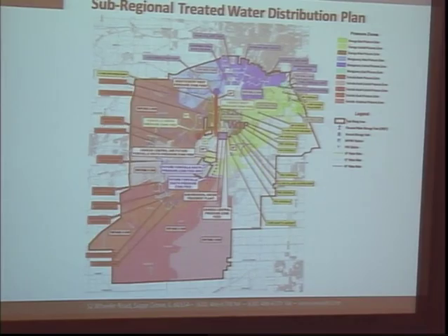The orange pumping gallery would come over and feed Yorkville. So in this instance, if the water treatment plant was south of the river, you'd have the Fox River crossing, and then going west to Yorkville. Off of that spine can also feed Oswego's west pressure zone. To the south, did something come up? There it is. Oswego also would have another feed down coming off of the water treatment plant here. And then Oswego would be able to come off of the red pumping gallery for transmission of the water to their zone as well.